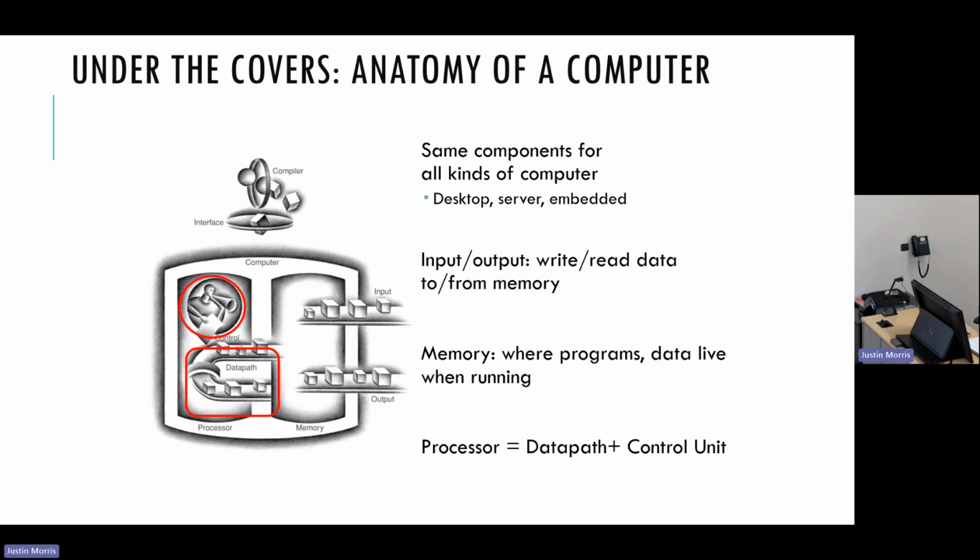And also a lot of the time, especially for big data applications, like machine learning, the moving of the data from memory to the processor can be a lot of energy wasted. So some machine learning workloads will be very data heavy, and in processors, usually load word, store word are the most energy intensive instructions.